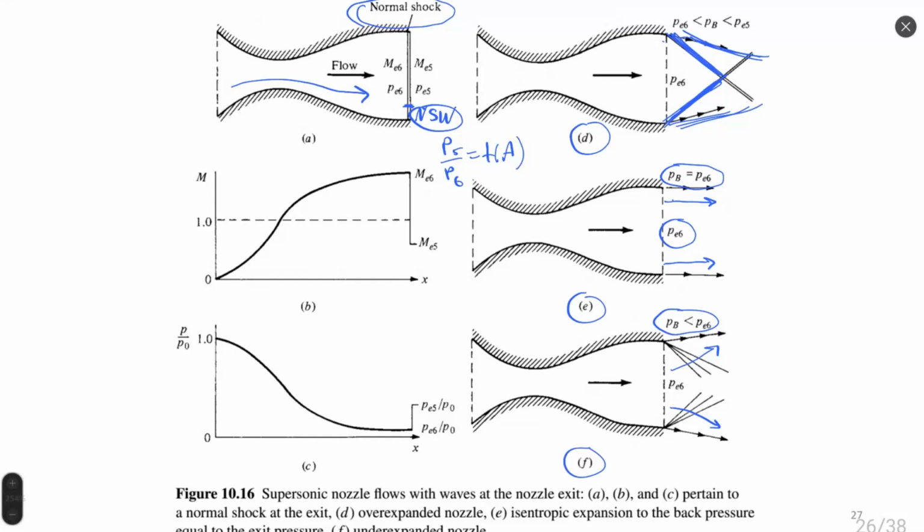Then at some altitude, the pressure equilibrates with the pressure of the nozzle. So we can see flow absolutely parallel to the nozzle flow, case E, at some altitude. I think it's an altitude of 5 kilometers, more or less, or similar. I don't know exactly because they change the pressure inside the chamber. They regulate the pressure inside the chamber, so we cannot definitively say at which moment exactly this pressure will equilibrate, but at some point it definitely happens. So you can see flow absolutely parallel to the atmosphere.